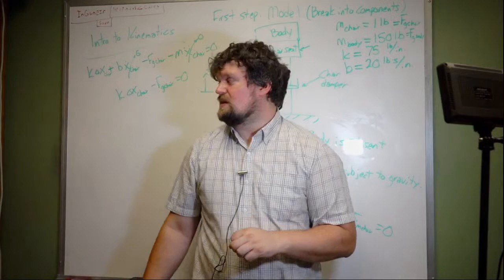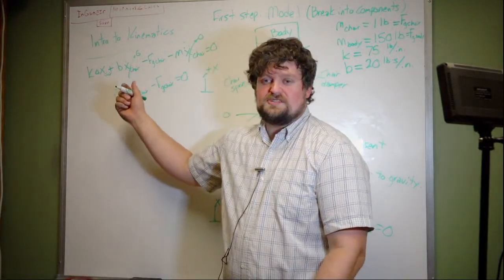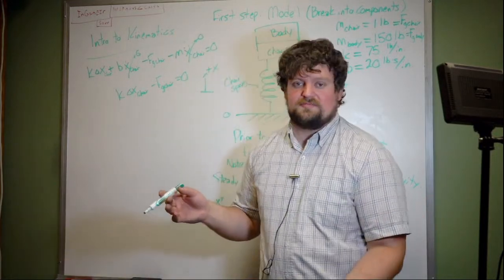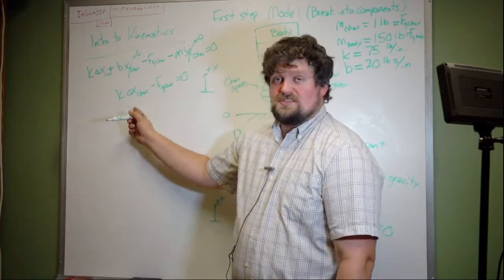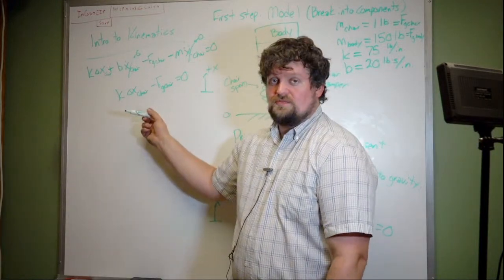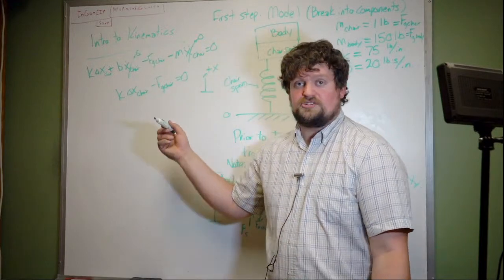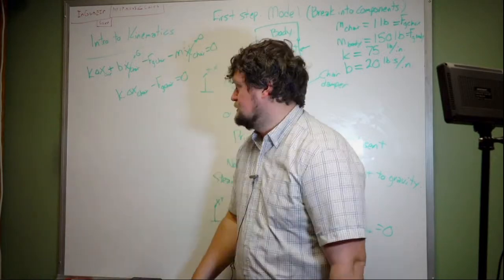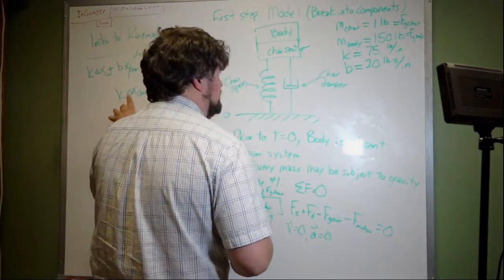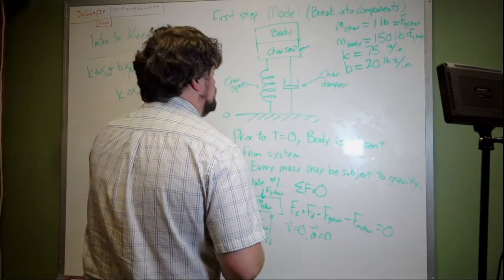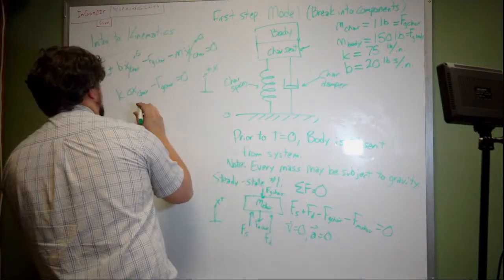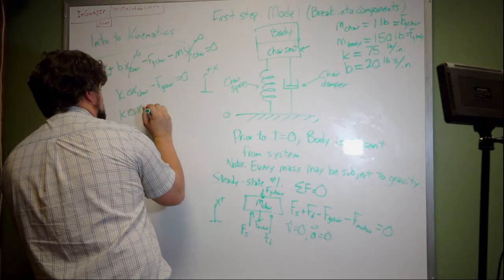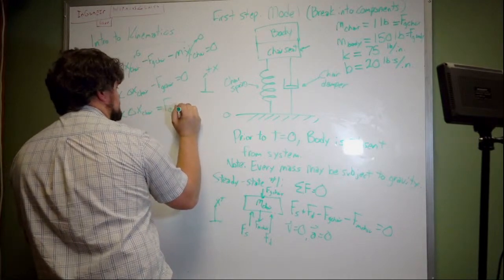Okay, basically what that means is that this chair is going to have some displacement relative to the original length of that spring that's unloaded, and that is the delta x. And this value multiplied by the spring constant is going to be equal to how much the chair actually weighs. So if we were to take the chair seat out, the chair would extend just a small amount. Okay, so this one is 75 pounds per inch. This one here is 1 pound. So we have, just going to set it on both sides, K delta x chair is equal to fg chair.